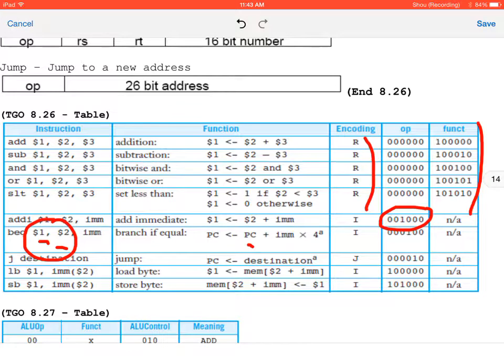typical branch, if statement. If A equals B, right? I'm sorry, A does not equal B. If A does not equal B, you want to do the value inside, right? That means you branch if they're equal. So in this case, let's say you have to skip 7 instructions. In this case, since it's an 8-bit data path, the value is going to be 7.